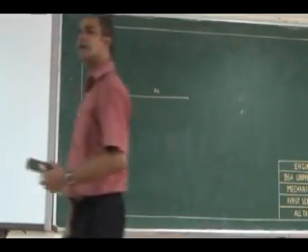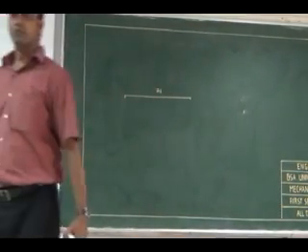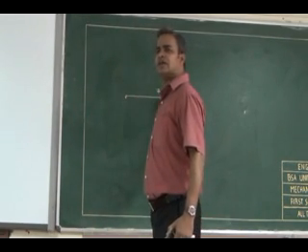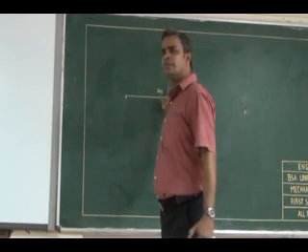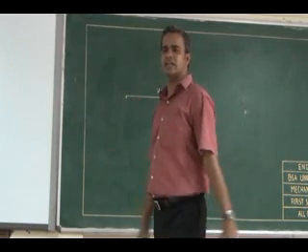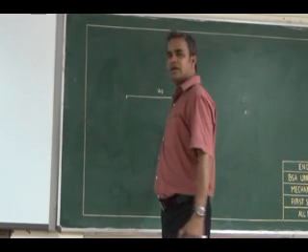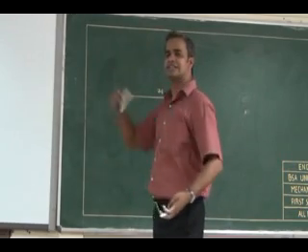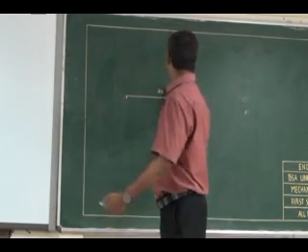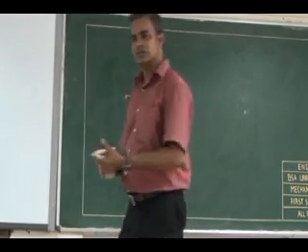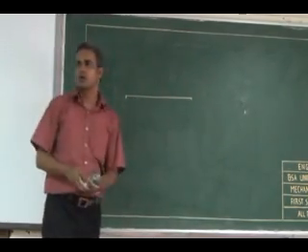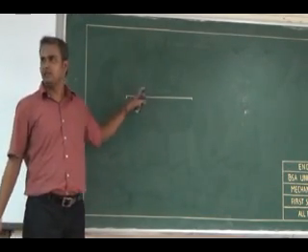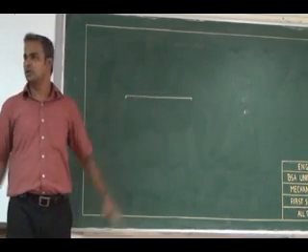If I divide 70 by 9, I will get some value. If it is a perfect number, I can divide it directly using my scale itself. But now, dividing 70 into 9 equal parts, I have to go for a constructional procedure. What is the construction procedure? Listen carefully. This is my original line, and I want to divide it into 9 equal parts.